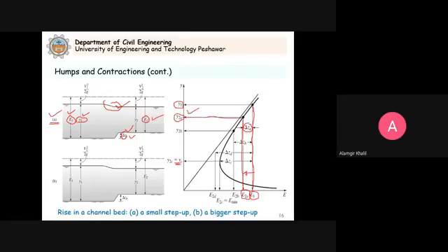For this specific energy, this is also the possible depth. But if this depth has to be corrected, then it has to pass below the critical depth, and if it flows like this, then in that case this will be the correct depth. But since it does not pass through the critical depth to become the supercritical depth, in this diagram this is incorrect. Clear? So the flow still remains subcritical, and Y2A is the correct depth.